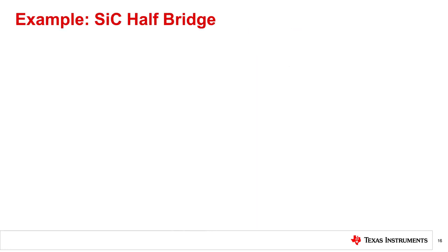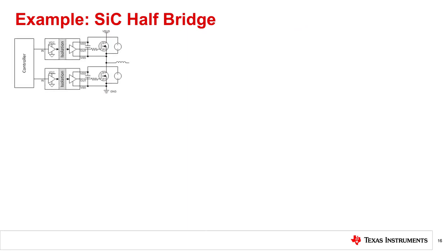Here is an example that integrates the lecture topics using a silicon carbide MOSFET half-bridge. Suppose that for our combination of drain current, load inductance, and gate drive characteristics, we can expect turn-on and turn-off times of no less than 25 nanoseconds and no greater than 35 nanoseconds. We can also expect the rise and fall times to be 10 nanoseconds and 8 nanoseconds respectively. These parameters are relatively stable over temperature, and the 800-volt bus voltage is unchanging.